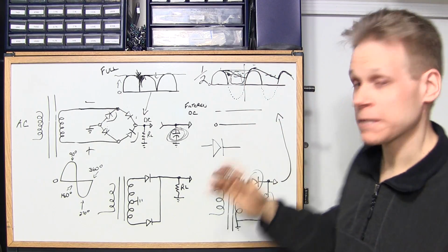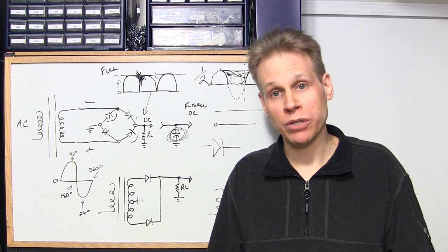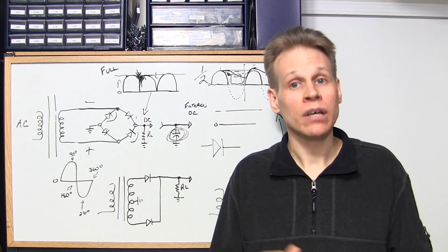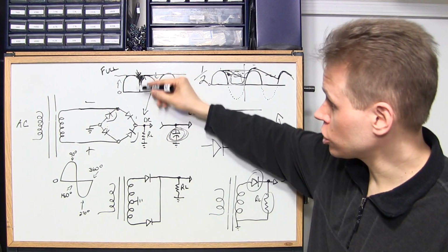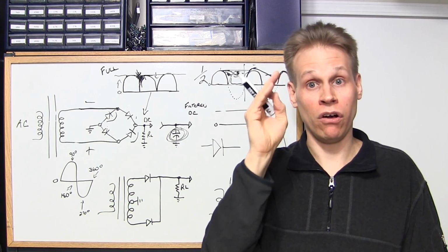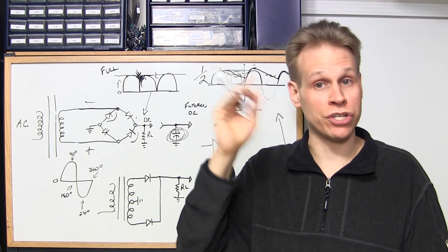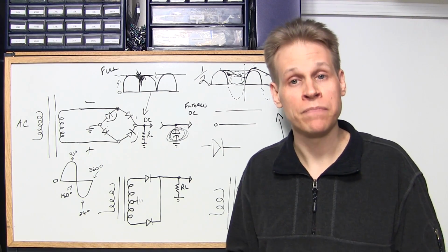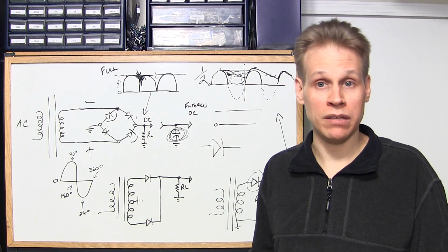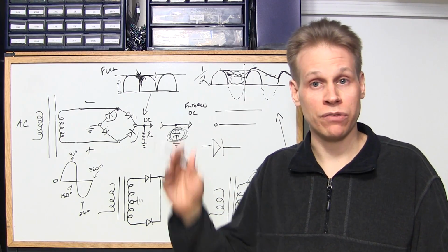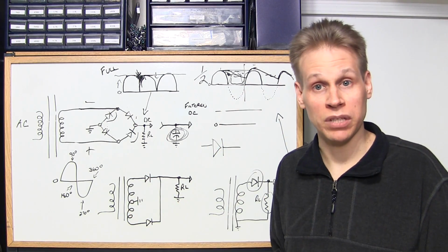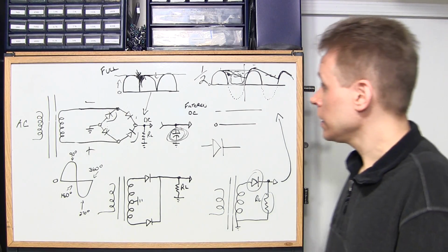Now you'll also notice in some of the really large switch mode power supplies, they've got really low value capacitors, and you're thinking, well, how come they've got smaller capacitors? Well, they run at such a high frequency that this is reoccurring so incredibly fast that you don't need all that capacitance, because it's there all the time. It's recharging that cap at an incredible speed. That's why in really high frequency switch mode power supplies, you don't see that many microfarads on the capacitors. It really is quite low. So that's the reason for that, just the speed. All right. So that's that.